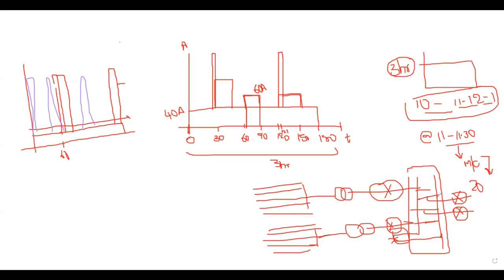If we take an example from our everyday life, suppose I want to install an inverter and battery in our home. Then I will check what the lights are, what the fans are in my hall, bedrooms, kitchen, right? I take all the loads and consider which loads will generally be on when the power is lost.